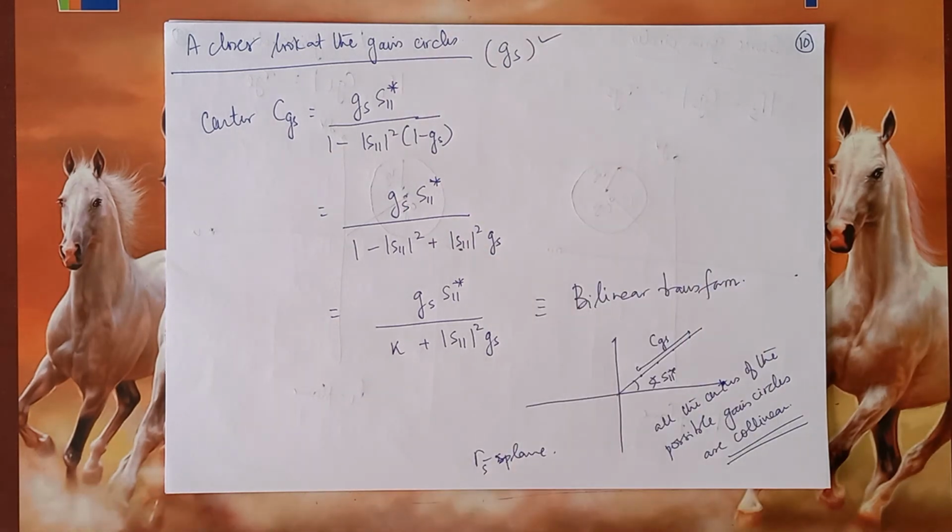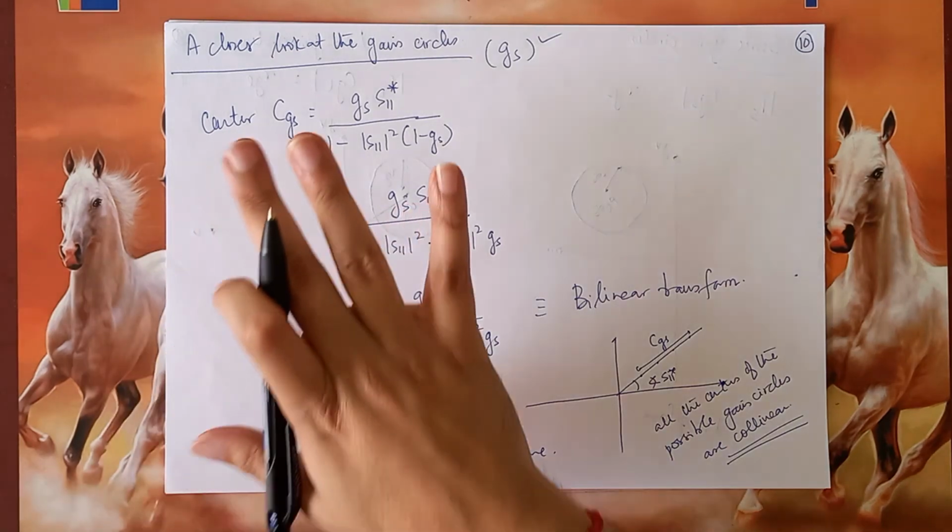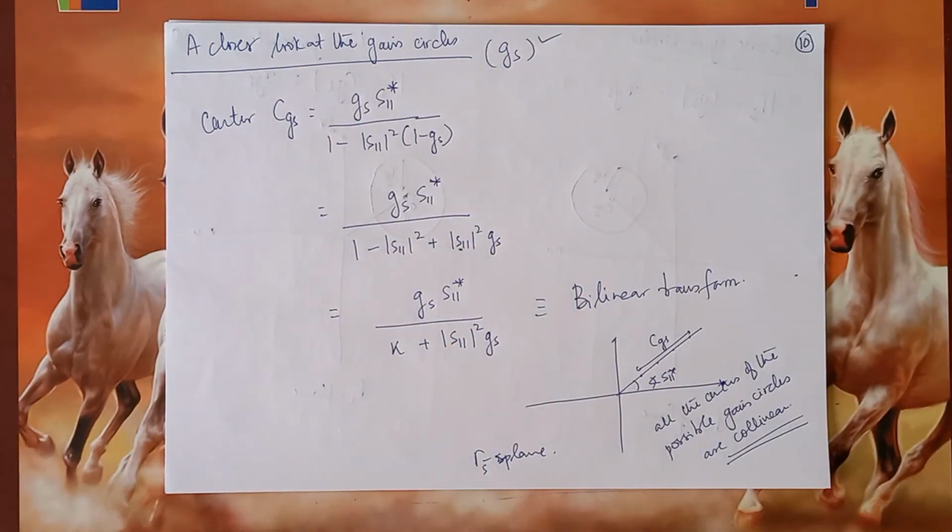So to compensate for the error, we defined a term called the unilateral figure of merit. The smaller, the better, which indicates the error between the unilateral gain versus the actual gain. And from that unilateral gain, we discussed the gain contribution of the source side and the load side. And using those, we saw we can achieve our desired values of gain by constructing gain circles.